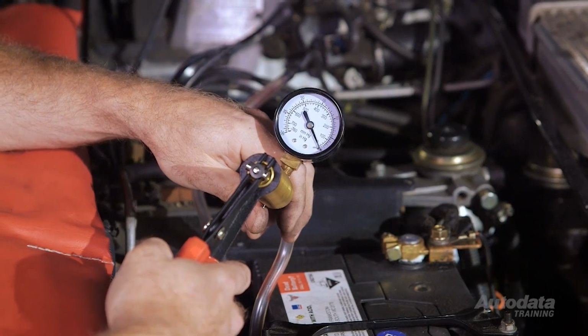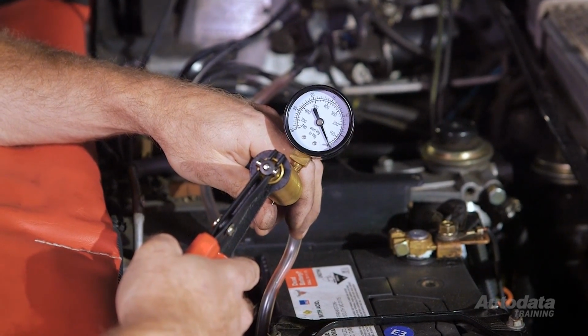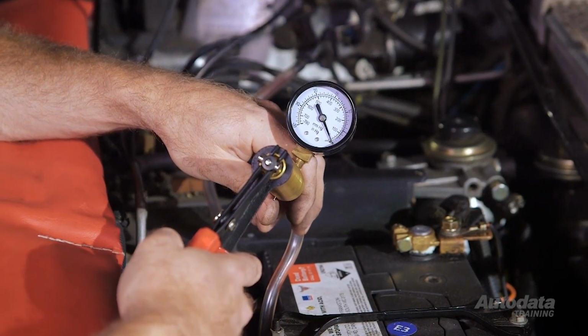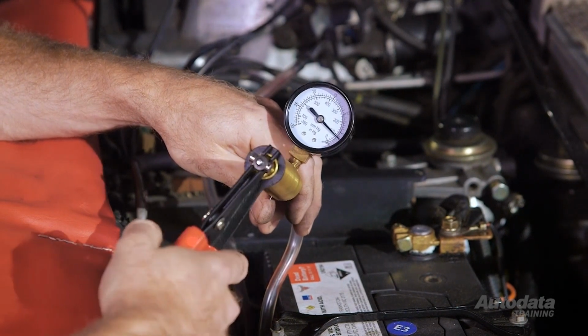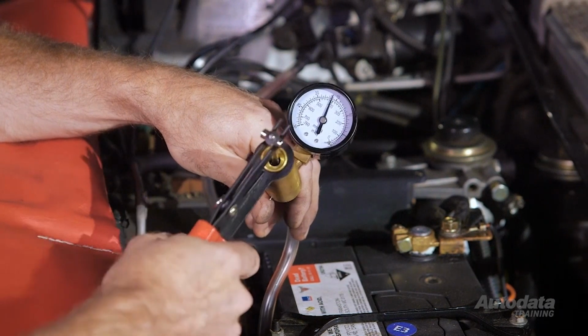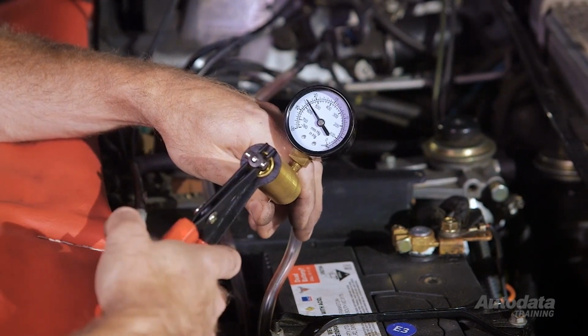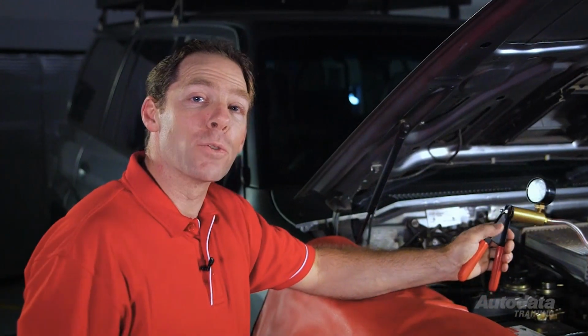Connect a hand-operated vacuum pump to the EGR diaphragm port, start the engine and allow it to idle. Apply vacuum and listen to the engine. On a diesel, you should detect a change in the engine note as exhaust gas is pulled into the intake manifold past the pintle valve. On a petrol vehicle, the engine should stall. This is because the fuel mixture is enriched with exhaust gas and it's unable to continue idling.